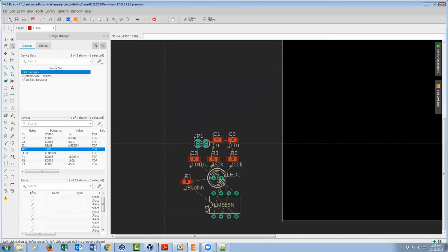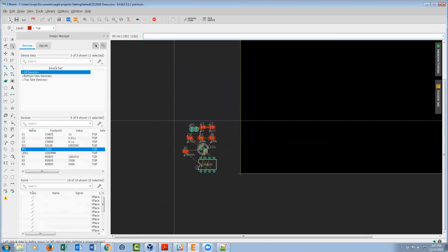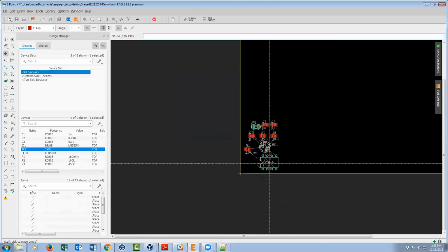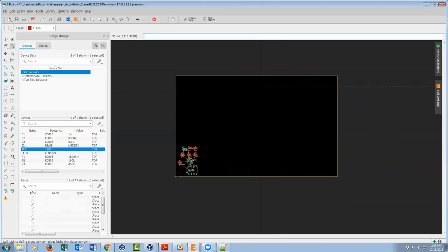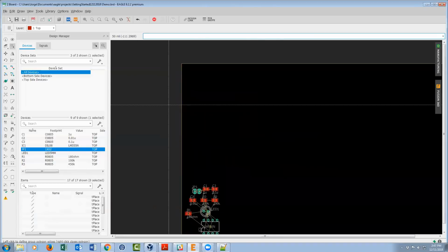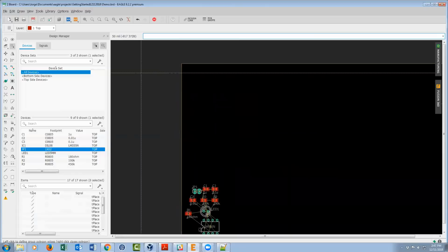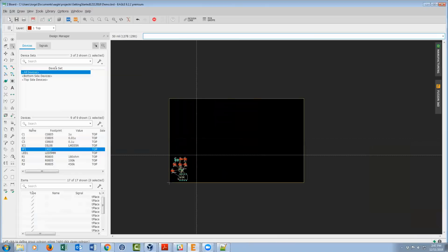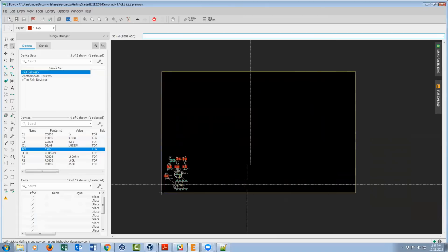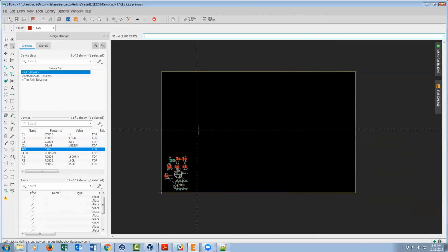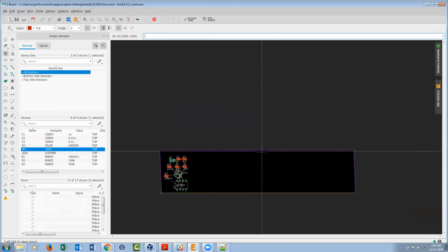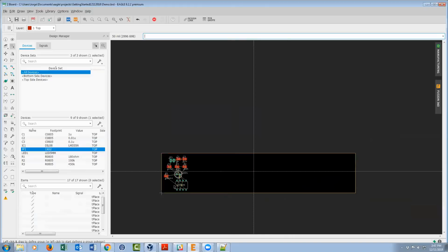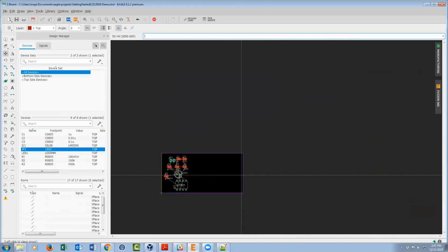Okay. So what I'm going to do now is take these components and bring them into the design. And I'm going to drag this outline. Now, one thing you're going to notice is a difference in color. The inside of the board is black, whereas the outside is a dark gray. This is the board detect feature. It basically recognizes that this is a board outline, and it accepts it as a valid outline. This becomes important if you're going to work with Fusion 360, which again is for another video. So I'm going to go ahead and shrink this.